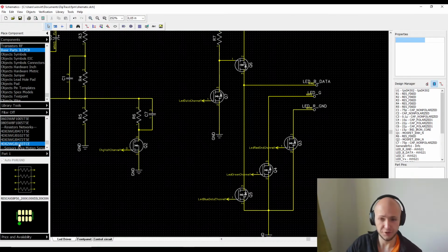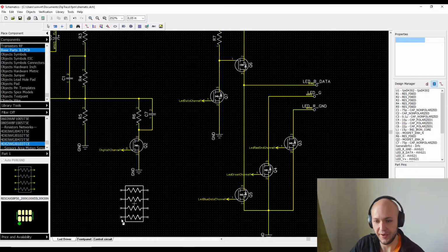I'm still thinking about using resistor networks to handle fewer resistors, because they are physically bigger than normal resistors. And it's easier to work with them, it's nicer. You have less to do, less to worry about. And assembly is cheaper too.